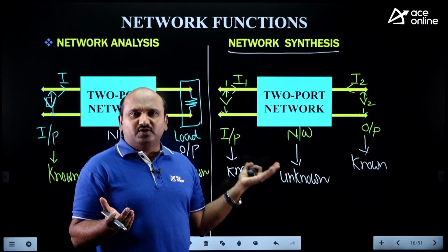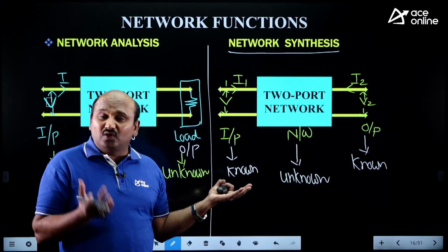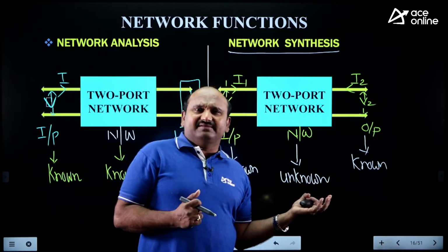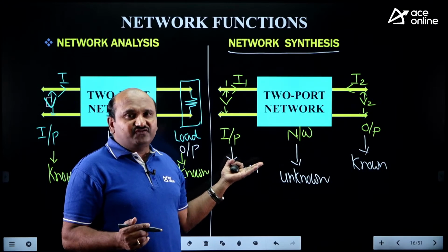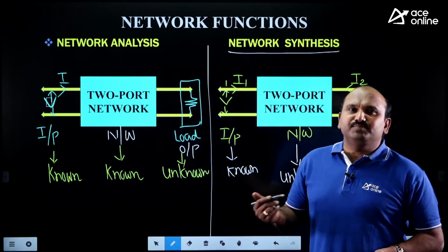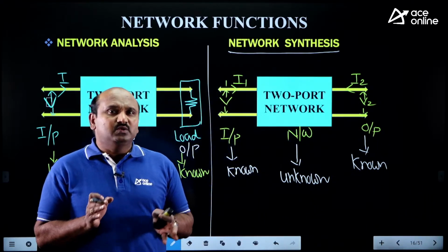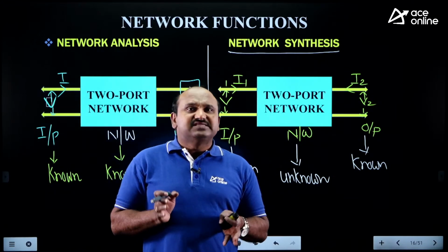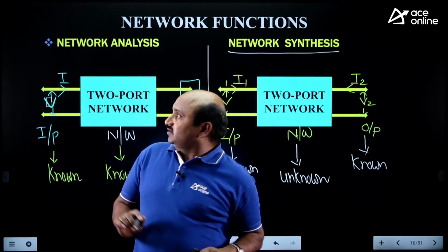While coming to the two port network, we have the transfer functions also, and gains also, current gain, voltage gain. These are all we are having under two-port network, but one-port network we have only driving point functions. Using the driving point, either impedance or admittance, how to realize the network, how to design the network, how to synthesize the network by knowing that input and output.